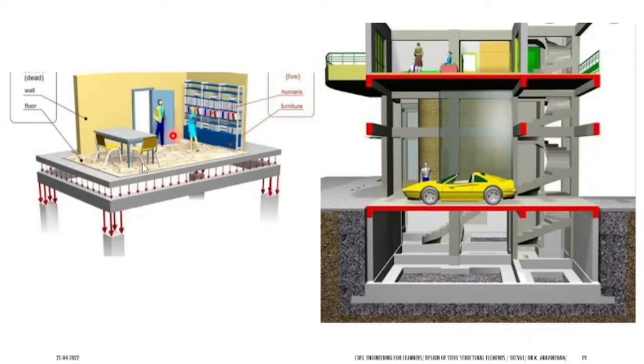What is the highest weight? You can have a bureau or a cot. So what will be the highest weight of the cot or the bureau? 60, 50, up to 100 kg it can go. So can you take 100 kg as your maximum? Yes, but the code says you can imagine up to 200 kg. At the worst case, they are giving the worst case that not more than 200 kg is used anywhere in India, in any of your houses.